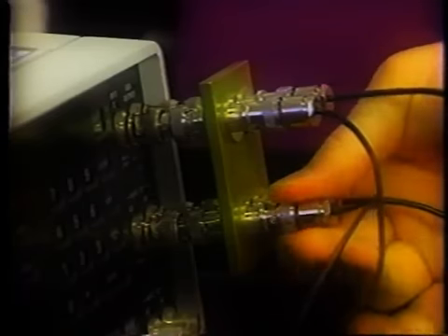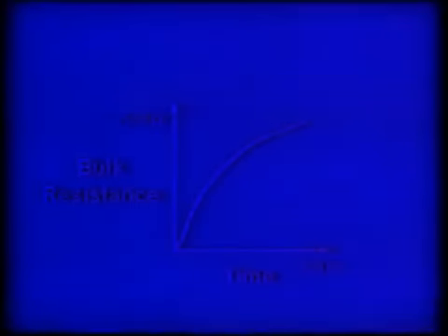The electrical properties of cement or mortar samples can be followed over time, leading to profiles of changes in electrical resistance. The electrical properties of this cement specimen are being measured using the two metal electrodes and equipment that measures resistance and impedance. This chart illustrates how the resistance of electricity through the cement increases as the cement hydrates.